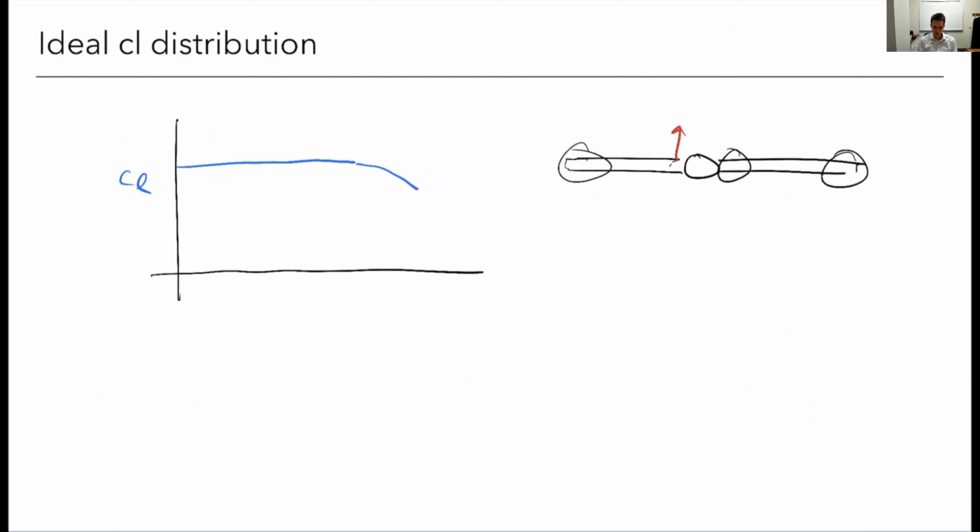And so in your case, you're going to want a lift coefficient distribution that's more like this, right? Where if it's the same airfoil, it's relatively constant inboard, and then it drops somewhat towards the tips. That's going to mean that stall is going to occur somewhere inboard and not out by the tip. The other reason why we don't want it out by the tip is that that's where our ailerons are going to be. And ailerons are out there for the same reason, right?